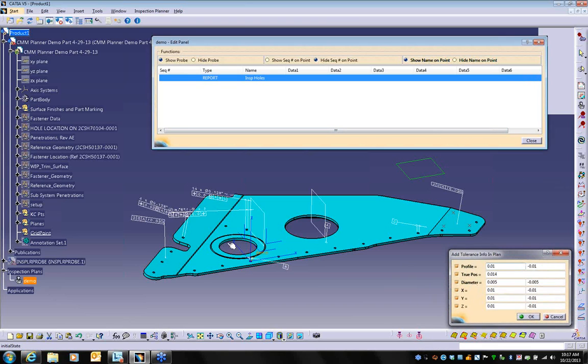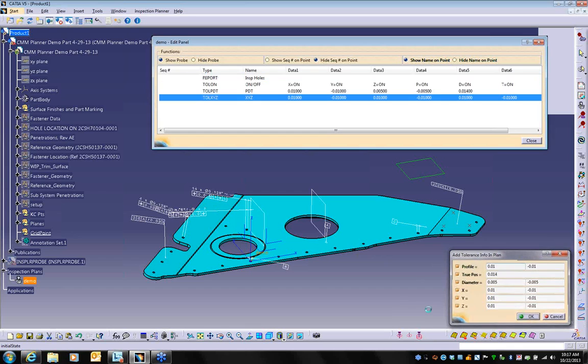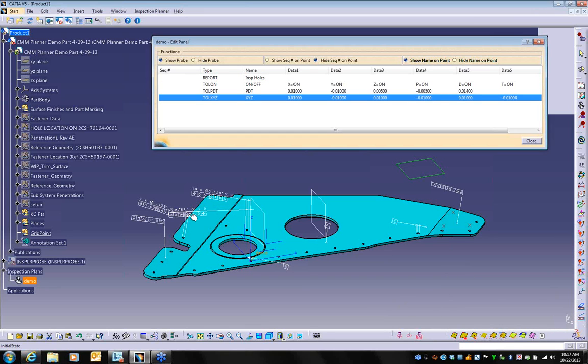We have a tolerance button, so we're seeing the FT&A in the model, and we can create the tolerances based on the model. If you are working with an IGES or STEP file, you would not see this FT&A or MBD information in the model. So we get to work with the MBD that's in the CATIA model.